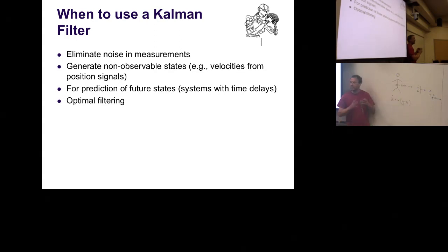The same idea you can use to create more complicated filters, and I'll talk about this with polynomials, which have much better properties. But it's the same idea. You basically use some kind of smoothing, which delays your system a little bit, but then you get rid of the high-frequency spikes in your data, which you assume is noise. You can do this in a more principled way with proper digital filtering. But using a model is a much better way of doing it, since you can actually predict things based on the model, and that's where you don't get as much delay, for instance.